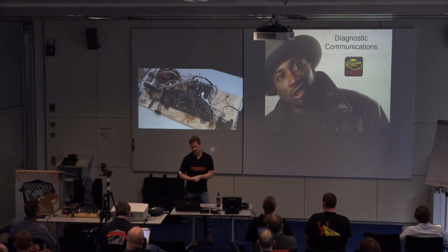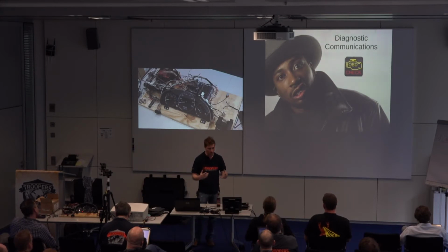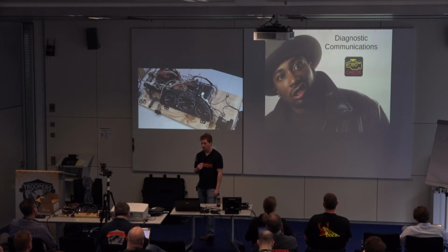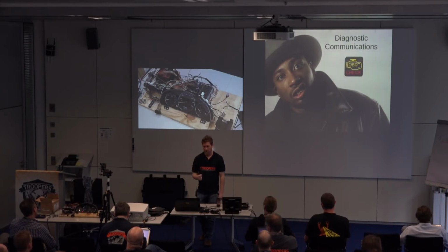And so diagnostic communications are typically what you use if you get a phone app and you want to plug in a little cheap dongle to the underside of your car. That's what this is going to use. And we can manipulate the exact same thing, we're just not going to use the appropriate protocol. And so this also runs on CAN. It runs a little bit differently on CAN, but it runs on CAN.